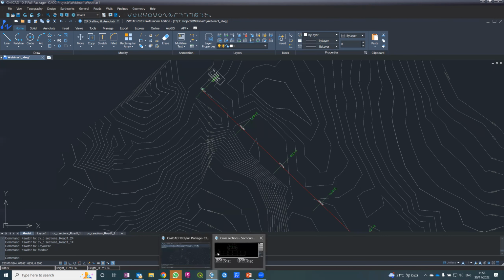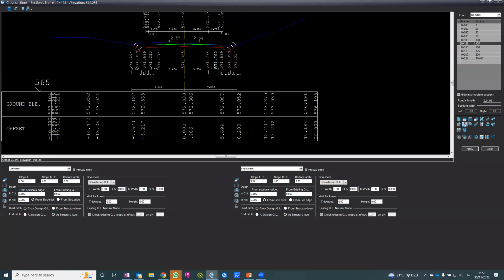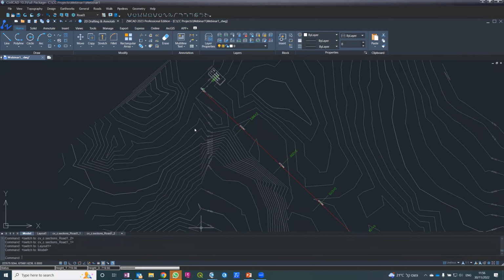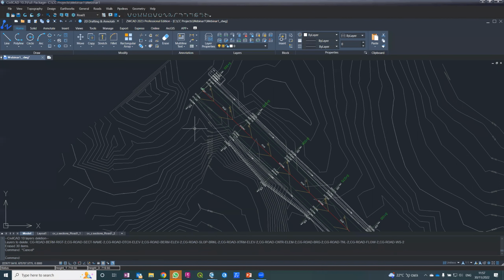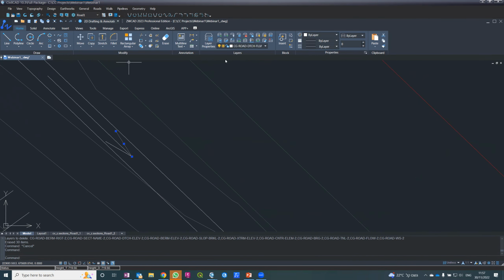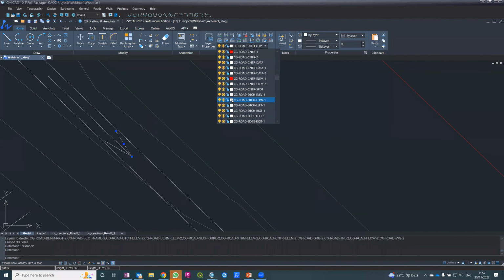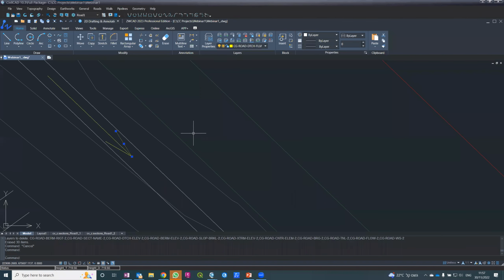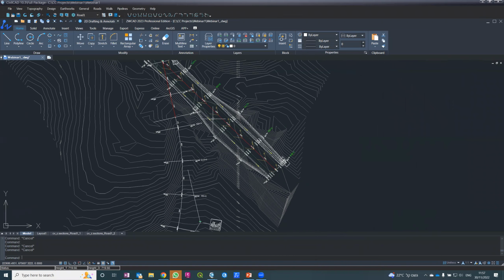Okay, what I want to do now is tell the software also project this design on the full layout with a 3D surface, full corridor. Now I've received a full corridor along this road. A full corridor along this road with all the data, and the ditch, you see it start from here, going down, the flow direction. This flow direction goes here. Good.